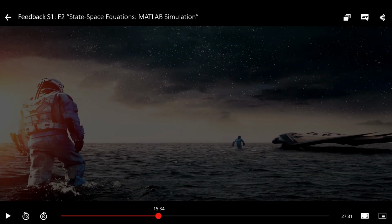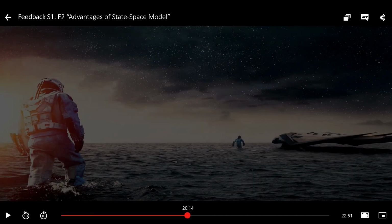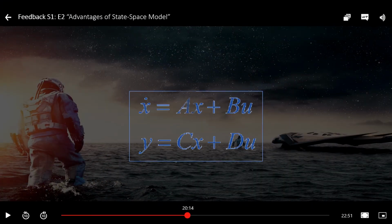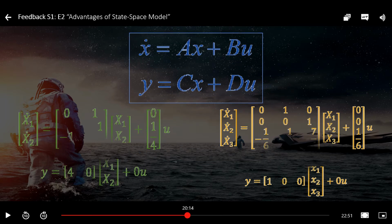Aside from manual computations, we also use the MATLAB software to generate the conversion of transfer function to state space to verify if the manual computations are correct. As systems become more complex, representing them with differential equations or transfer functions becomes unwieldy. This is even more true if the system has multiple inputs and outputs. But the state space model alleviates this problem.